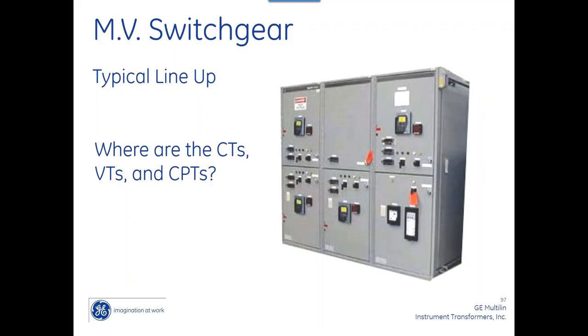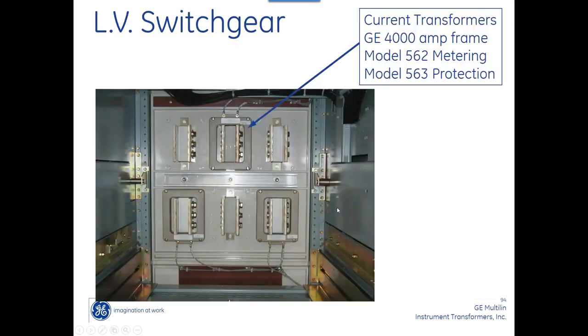Back on the slide with the staggered CTs. Can you stack the CTs? Yeah, I could put another CT. Depending on the depth of this bus bar, and depending on the manufacturer, you may be able to put 2 or 3 CTs on there.